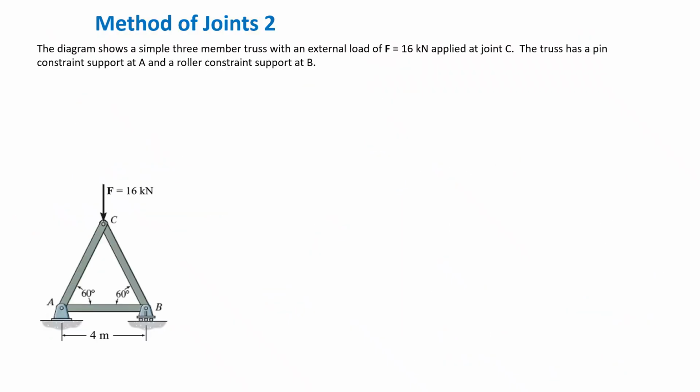I don't want you to read the question, but I want you to find the support reactions and the member forces. I'll give you time. You need to find the support reactions, like Ay or By or Cy. Yes, but in this one, the support reactions are really easy. Just by looking at this, you can tell me. Can you tell me? 8 each.